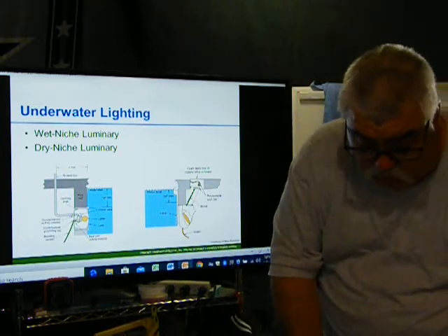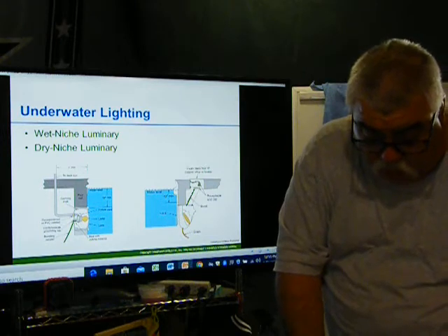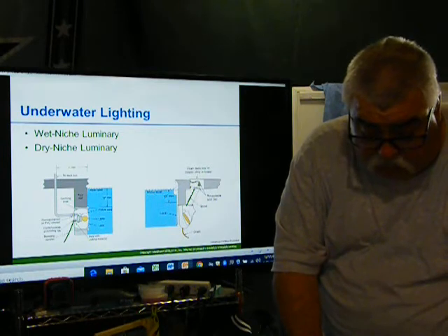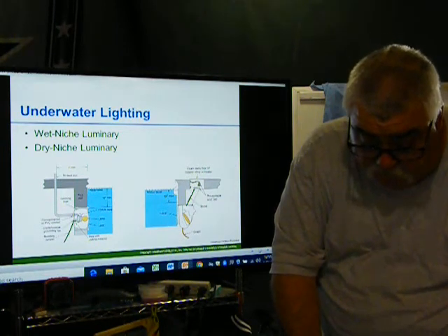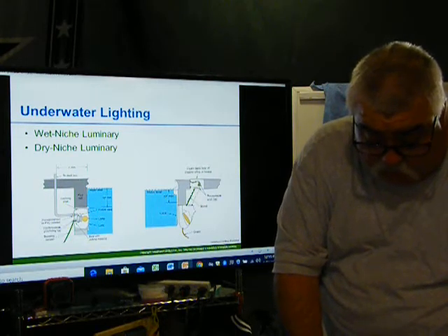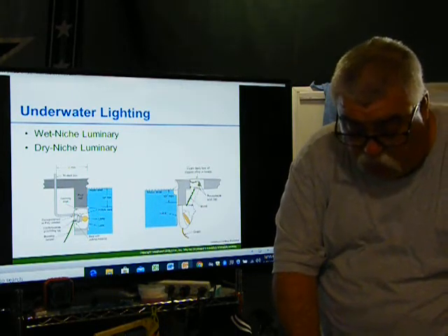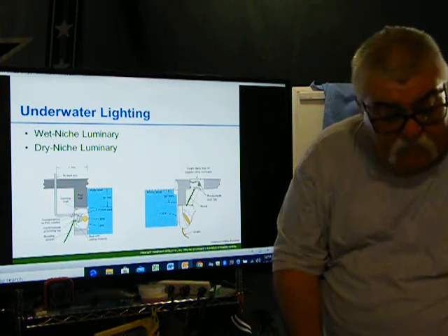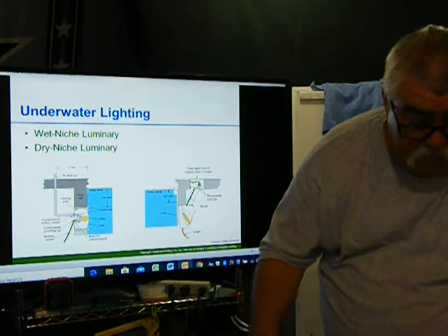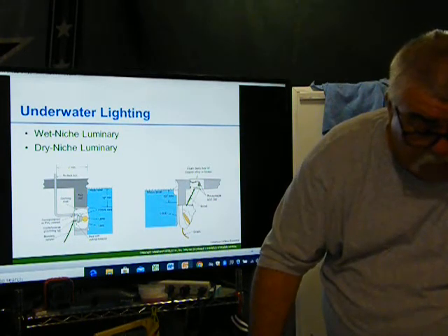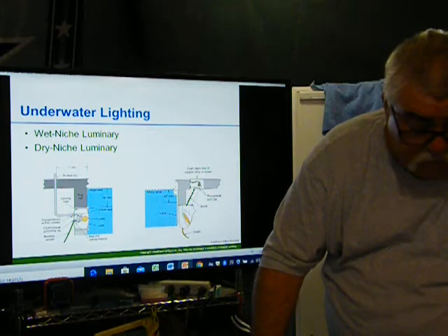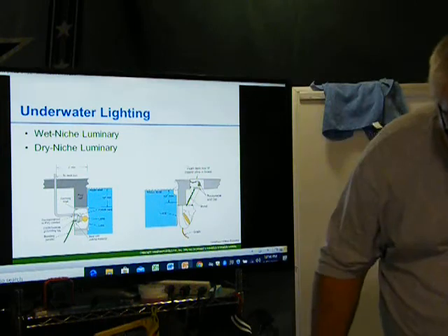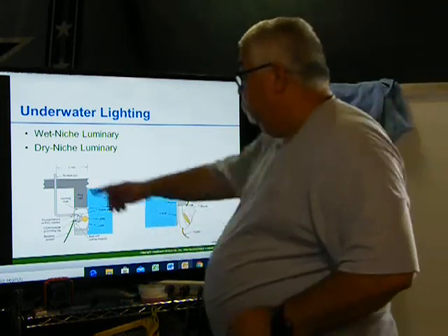Let me get in here real quick. It says the shell is equipped with a threaded port for conduit, which can be rigid metal, IMC, liquid-type flex, non-metallic, or PVC. Metallic conduits must be brass or other corrosion-resistant material. The forming shell has a lug for grounding and bonding the equipment ground conductor and bonding jumper to the ground grid attached to the lug. So we would pull a wire in.